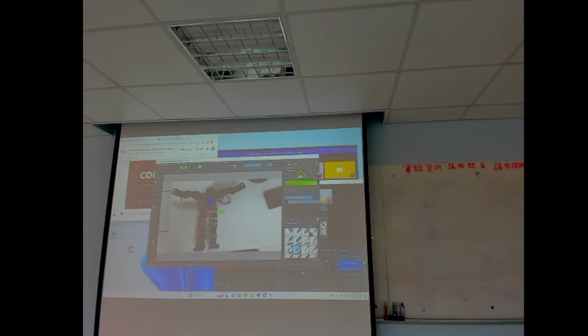Right, so then the next step, you want to look at the kinematics of your robot. Have a look at how many degrees of freedom you actually have. So for the right arm, we have 1 degree of freedom here, 1 degree of freedom here, 1 degree of freedom here. And then this is all fixed, there's nothing. So we have a total of 3 degrees of freedom in each arm.